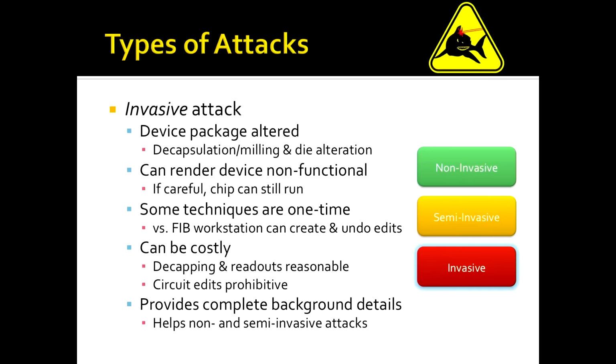So you can use all the floor plan data. You can actually force certain transistors or buses, circuit nets on and off, and get a good idea of how the device operates. And then you can feed this information back into the semi-invasive and non-invasive attacks to make them a lot easier, because you know where on the chip to target.